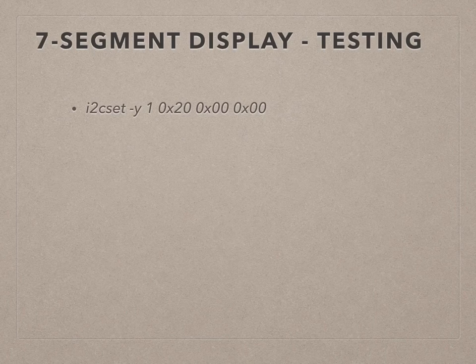From here, we can run a few tests by addressing our GPIO pins on the register 0x09 with any value we like. But for testing purposes, let's use some of the values from our table. I'm going to test by turning everything on first, using FF. This will help ensure that everything is connected as expected and that I don't have any issues with my circuit. I will then proceed to test digits 4 and 7 and then turn everything off again.